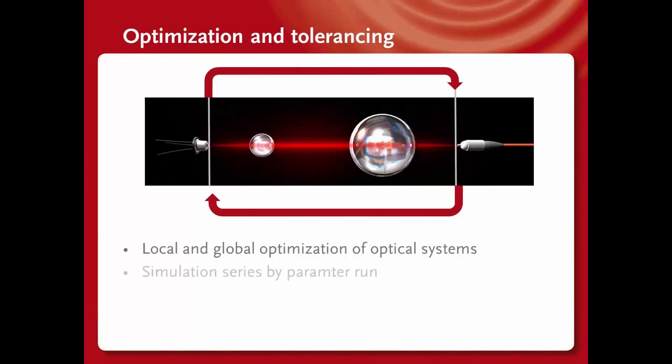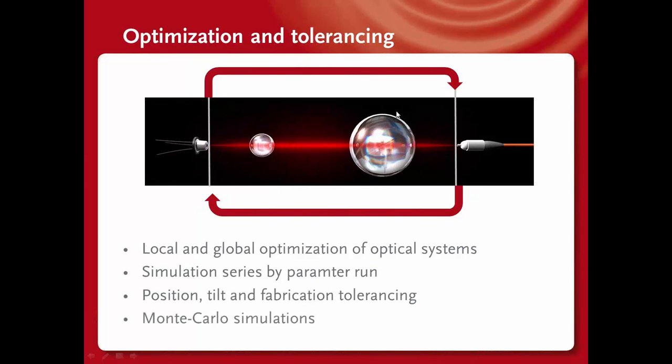That means that, for example, you start with a certain parameter set, propagate the pulse through the optical system, and get the pulse distribution in the target or detector plane. From this, you can calculate a merit function, and from this merit function, a local or global optimization algorithm can deduce the changes which are necessary to get a better result of your optical system.